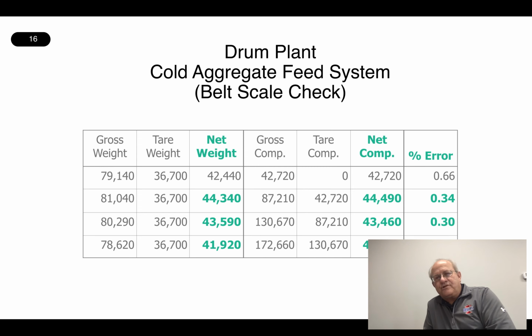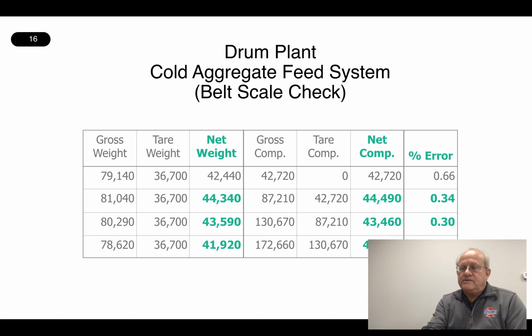Congratulations, you're within tolerance. Now, you can either not adjust the computer at this time, or if you think you can get a little closer, go ahead and do a calibration. Let it change its span numbers to get it a little closer. Now you can see it. In the next two, they did it both times. They got down to a 0.3% error and a 0.17% error.